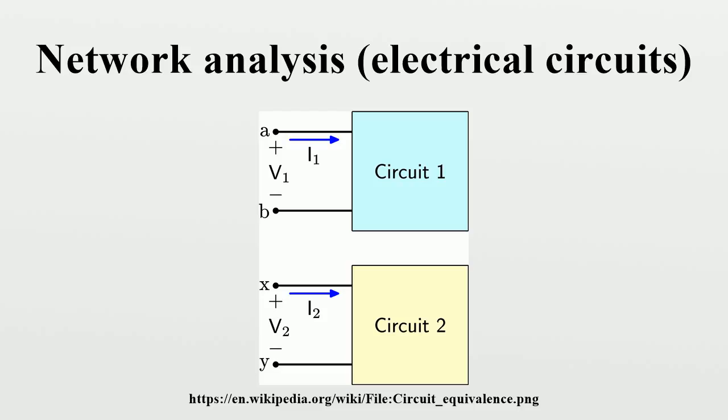General form of network node elimination. The star to delta and series resistor transformations are special cases of the general resistor network node elimination algorithm. Any node connected by resistors to nodes 1 to n can be replaced by resistors interconnecting the remaining nodes. The resistance between any two nodes is given by the following. For a star to delta, this reduces to the following.